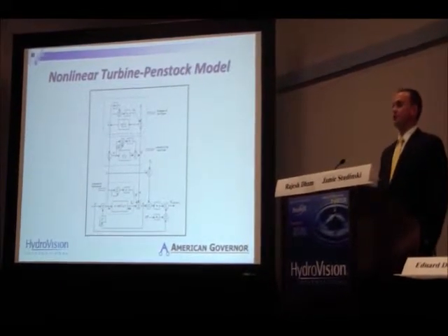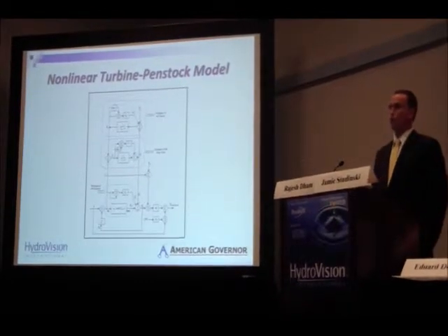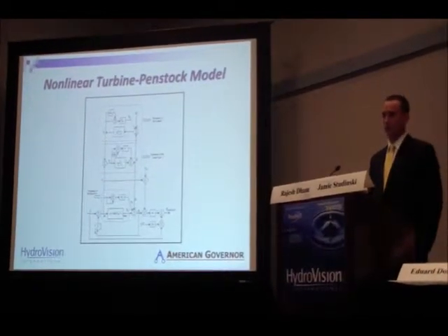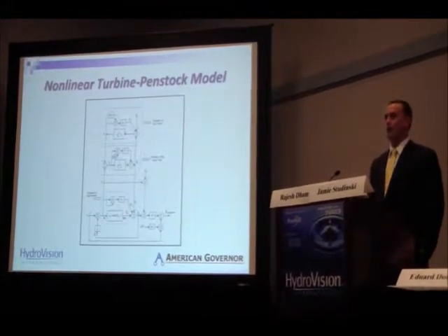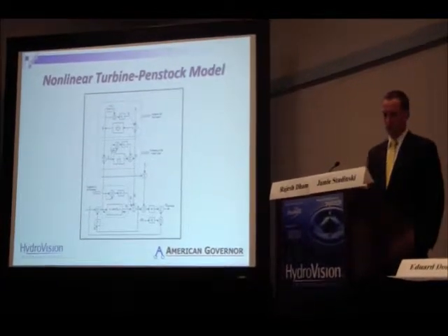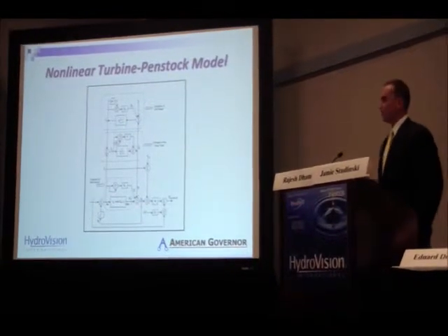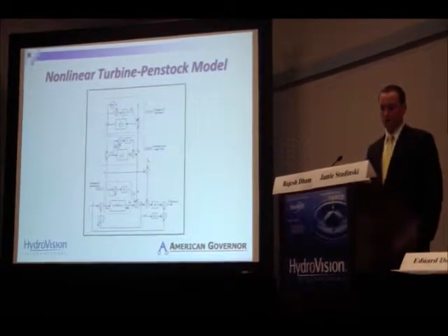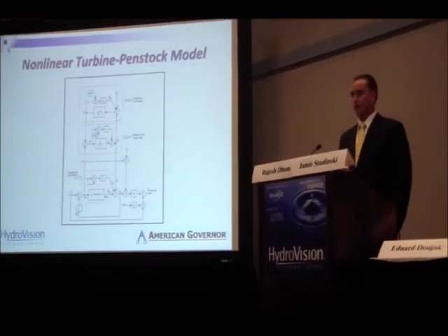Mainly, the consideration is that upstream of the surge tank, we can consider a water column flowing through that main feeder tunnel to be an inelastic water column, meaning that pressure fluctuations really aren't affecting the flow or the level of that water because we're sort of buffering those through a surge tank. Of course, then, in the middle section of this math model, we have dynamics accounting for the surge tank itself and how that affects water flow through the unit and how that affects, in turn, the speed of the unit.